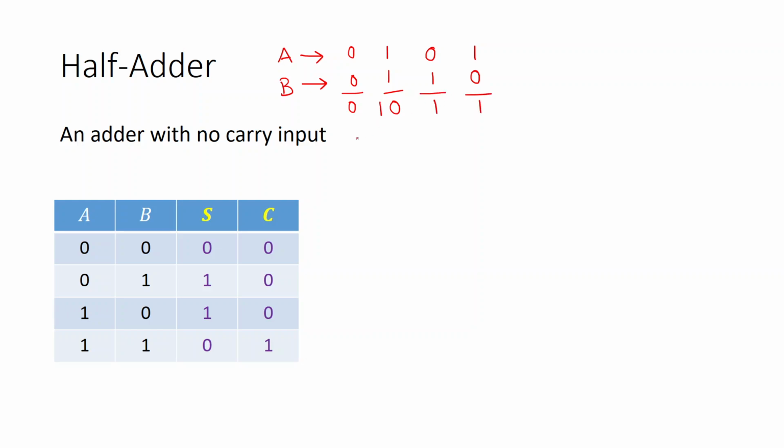This would give me a 1, this would give me a 1 with a carry of 0, with a carry of 0 here also. So there are two things, one is the carry bit, another is the sum bit or the result bit. So you see here, note down here, we have simply written this. So 0 and 0, if we add these 2 bits, what we are getting as the sum and the carry, and similarly for all other combinations we have written down the sum and the carry.